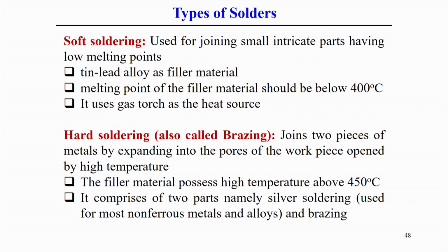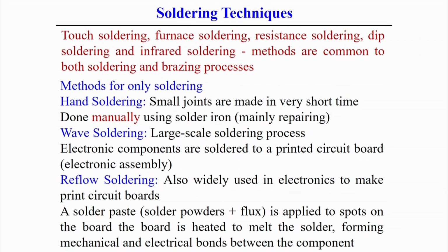In this case brazing is defined in terms of temperature as well as the filler materials used for brazing purposes. Normally soft soldering is what we call soldering in general, and hard soldering is in general part of the brazing process. Now we look into what the different soldering techniques are.